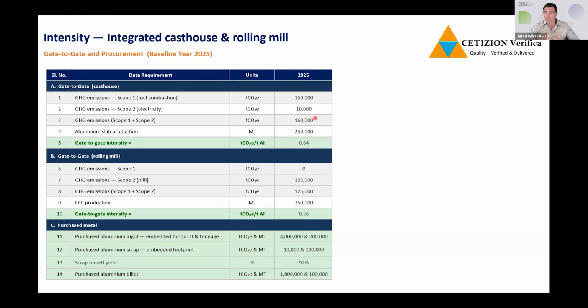The thing about the midstream is that you have your direct emissions, like for the foil rollers. By midstream I mean those creating extrusions, flat roll products, semi-fabricated products, often with an integrated cast house. There you have direct emissions from the cast house, scope 1 generally because they're thermal processes, and from the rolling mill or extrusion press, predominantly scope 2, using electricity. So the gathering of data is similar to foil rolling, but will be more dominated by scope 1.